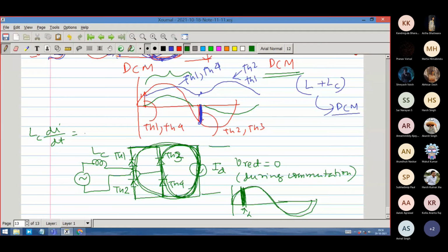That is the voltage here. And assuming that this duration is very small, you assume that sine alpha is almost constant, because this duration is called the mu duration, a very small duration, because commutation is happening. Because this value LC is not too large. It is existing, but it is like a non-ideal leakage inductance. This is called leakage inductance or commutating inductance, not large. So therefore this is a good enough equation. And what is this equation saying?